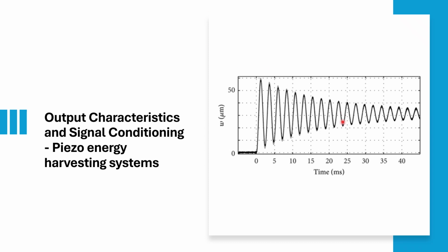This can be countered by making the element the same resonant frequency as the source of the mechanical vibrations, which can be done by varying the dimensions. The piezoelectric constant of the crystal is given in units of coulombs per Newton, and this value depends on the material the crystal is made of and its dimensions.